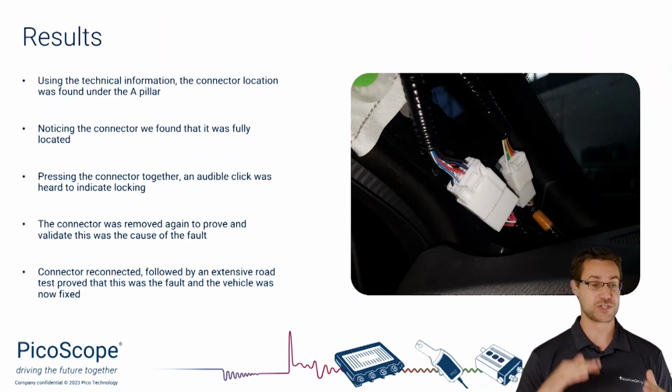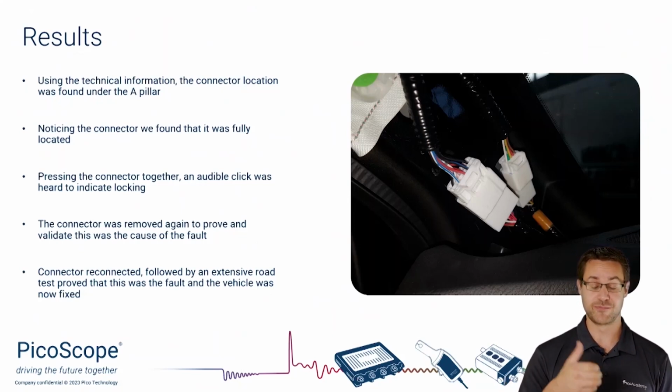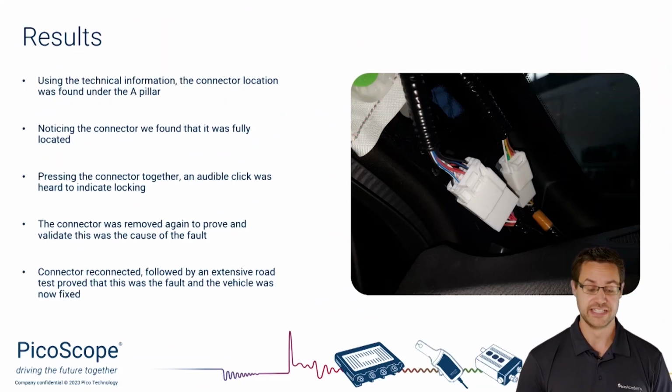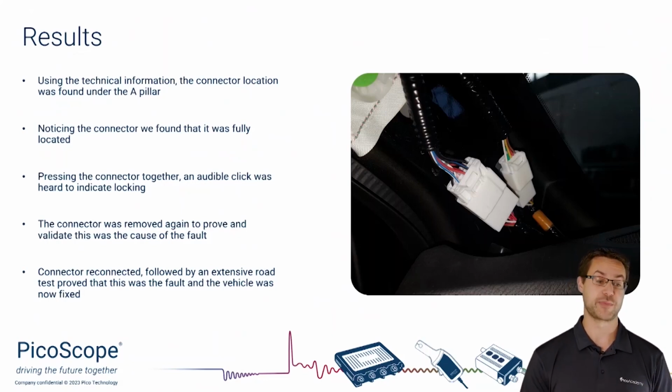Again, once you've come to a stop or cycled the ignition, that may have rested back again so that it's connecting with all of the terminals. Ignition back on again, everything's happy. So once we clipped it back in, we heard an audible click to indicate that it had locked together. Went out on a road test, and obviously the validation from your testing would be your next point of call, so go back over and make sure that the whole thing is working as expected.